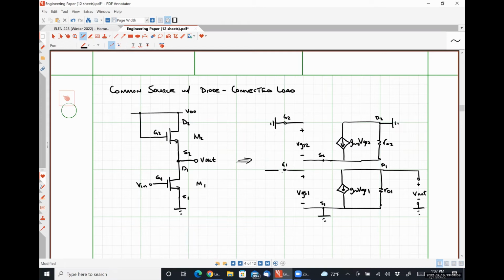And then over here on the input side of transistor M1, I obviously have my voltage VS. And my source for transistor 2 is connected to the drain of transistor 1. So I'm going to tie those two nodes together. How do we feel about this small signal one?